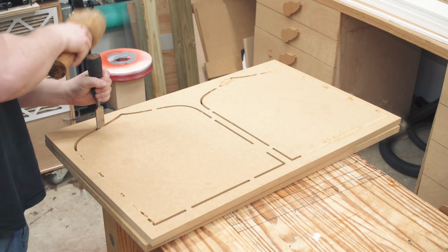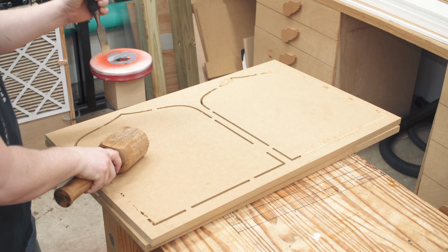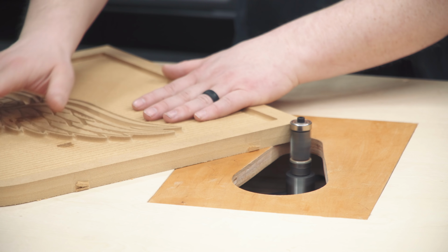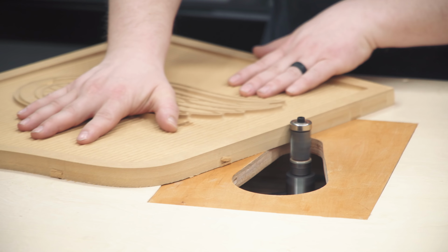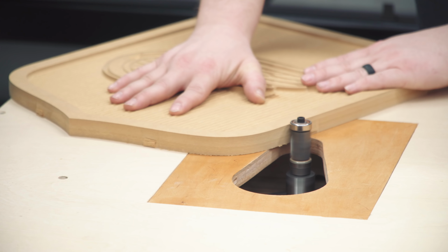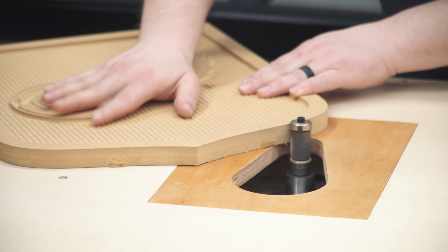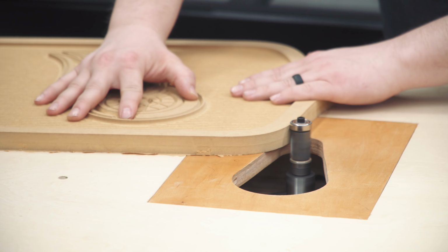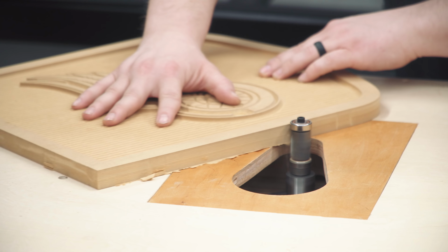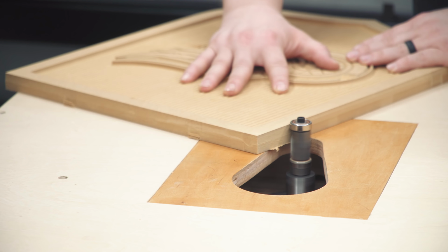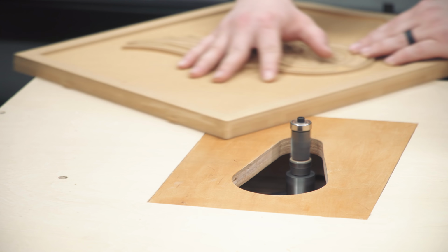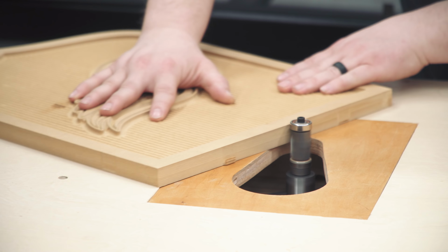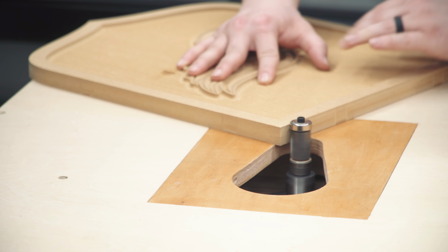Hopefully it won't. After all of the CNC cuts, the tabs are broken with a chisel and then flush trimmed with a router bit. And this is a compression flush trim router bit, so the bottom surface is being cut in the up direction, leaving a super clean edge. And I've gotten to where I use this bit so much that I kind of want to get a separate router table or something set up separately so I can leave this one 100% dedicated to this bit. I use this bit all the time.